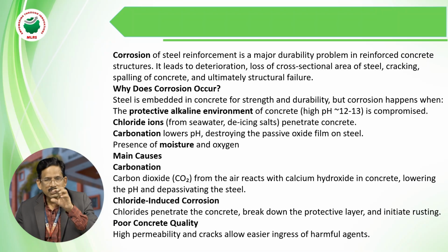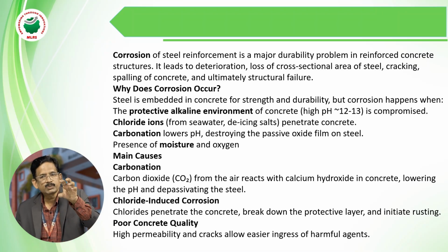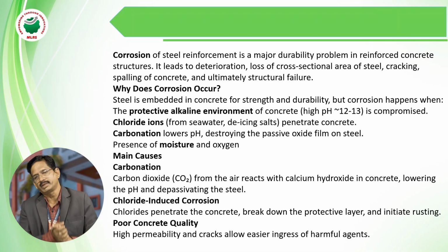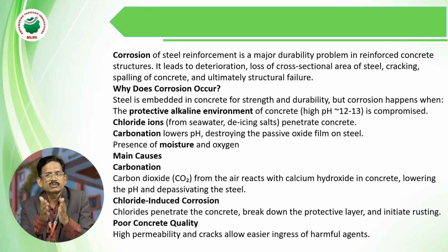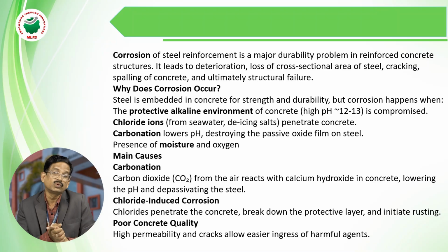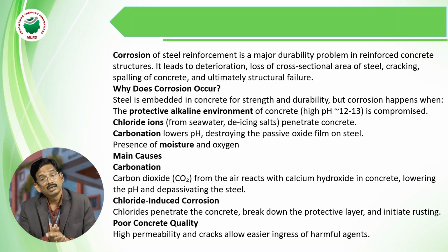If the reinforcement is corroded, the yield strength will be reduced. Suppose you design a structure for Fe 500 and the reinforcement corrodes, it may reduce to 450 or 400, so we won't get the desired values or the safe permissible values.